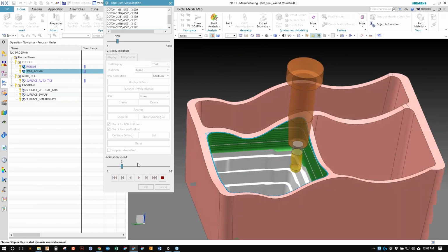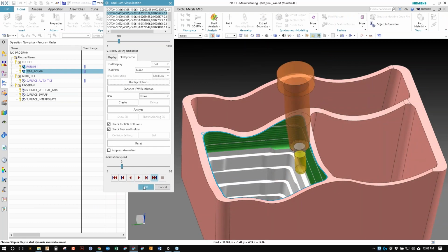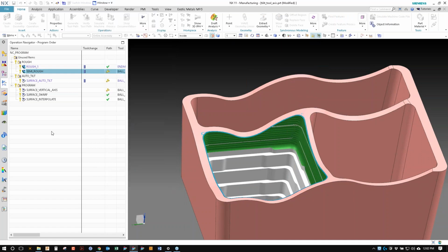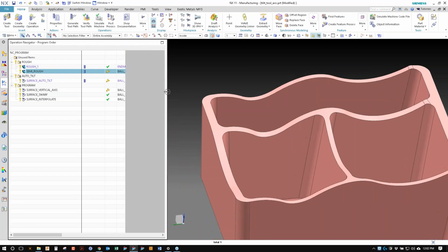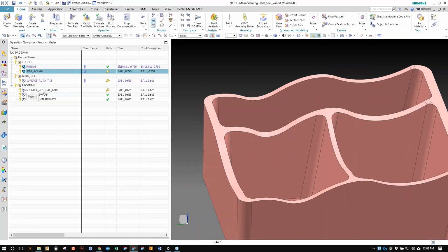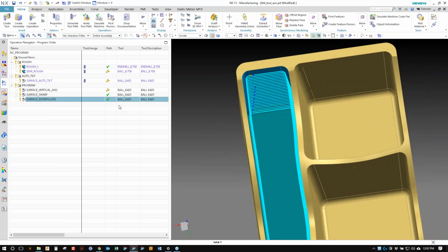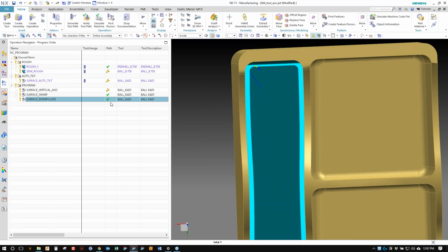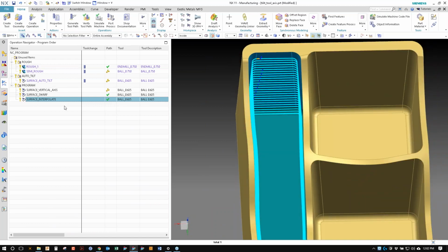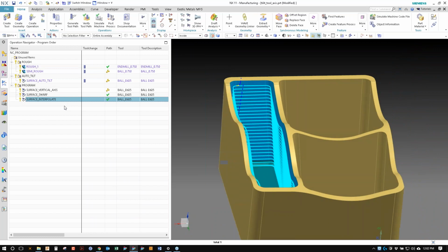So I've used that on roughing toolpaths before. I would say it is much smoother in 11 than I've seen previously. The version that I used it on, it worked, but it was a little scary to watch at the machine. So that is the automatic tilt tool axis, and then a couple other ways, also the interpolate tool vector. So both of those work well when you have tight spaces where you're getting a collision tool path or too much tool axis change with the other options available.